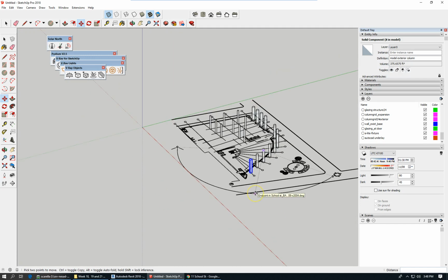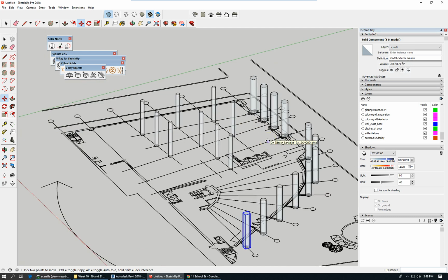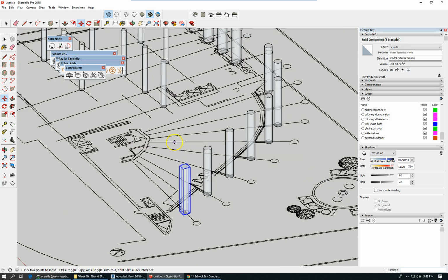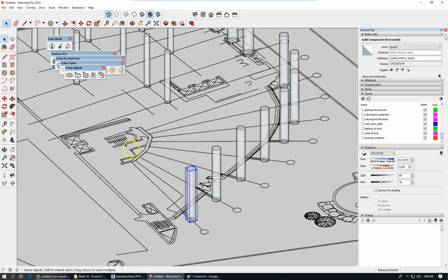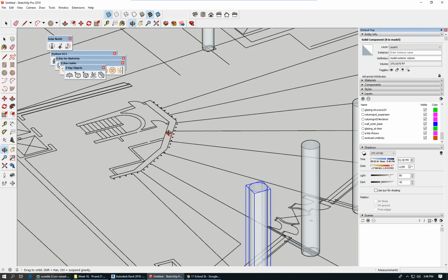So what have I done so far? I've created my understructure for the elements that occur on a column. Because of what I know about the model, I'm also going to add this bearing wall element, which is the wall on which the beams sit that has this shape.